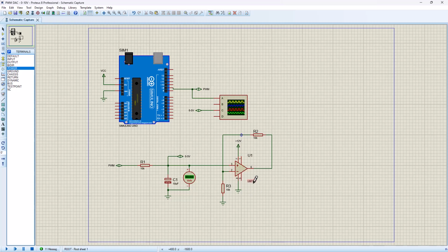Now the LM741 also has a voltage limit, a maximum voltage you can connect to it. So you cannot connect 100 volt to it, put a gain of 2 here and hope to get 200 volt on the output. That's not going to work for you. So in short, your op-amp would only amplify up to its terminal voltage, but it will not actually get to it. It will be just below the terminal voltage. Depending on the datasheet and the configuration of your op-amp, it might be 80% of its terminal, or 90%, or even 70%. So you have to check your op-amp datasheet.